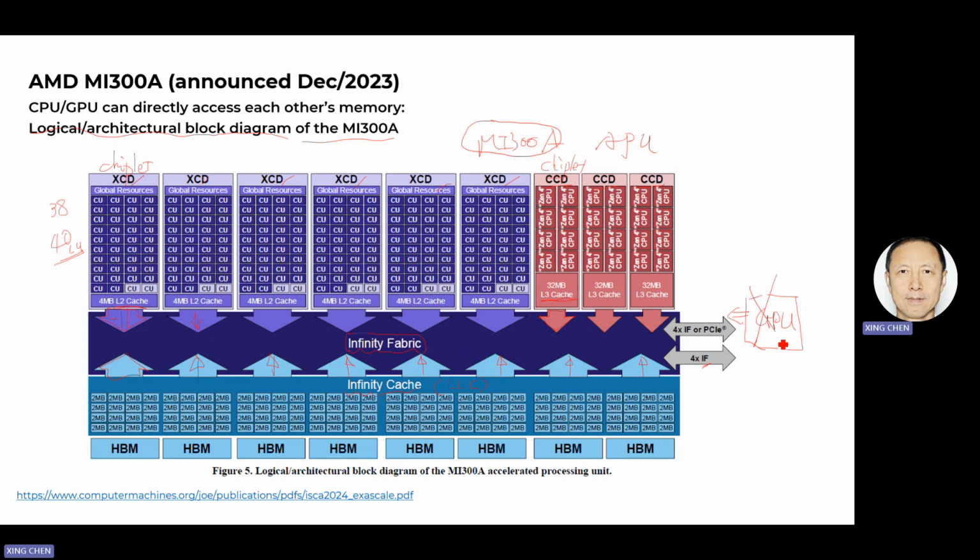What I mean is that with this kind of cache coherency enhancement and with PCIe links with the extended ATS service, the Nvidia GPU is still a PCIe component. But for the MI300A, the thing has been changed. The GPU is no more a PCIe equipment.